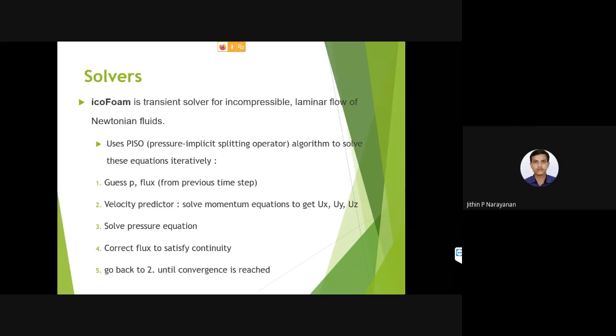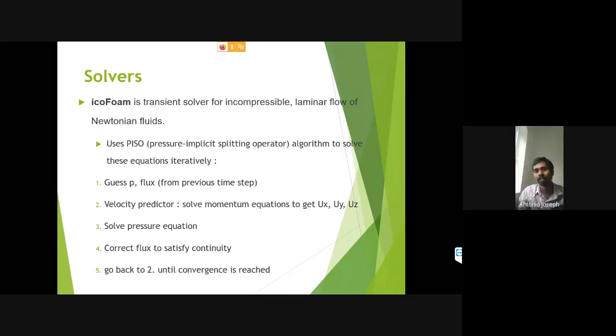Using this solver, we may not be able to capture turbulence values. We are not able to capture the turbulent values; we are only considering laminar in this case. There is mu t and mu tilde, which were discussed in the previous slide. They will be equal to zero. Those two files won't be there while solving with icoFoam, or else it will show an error.